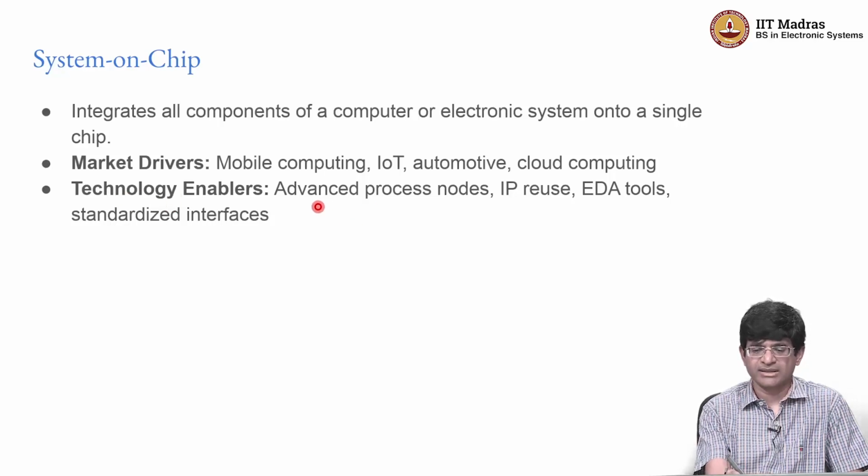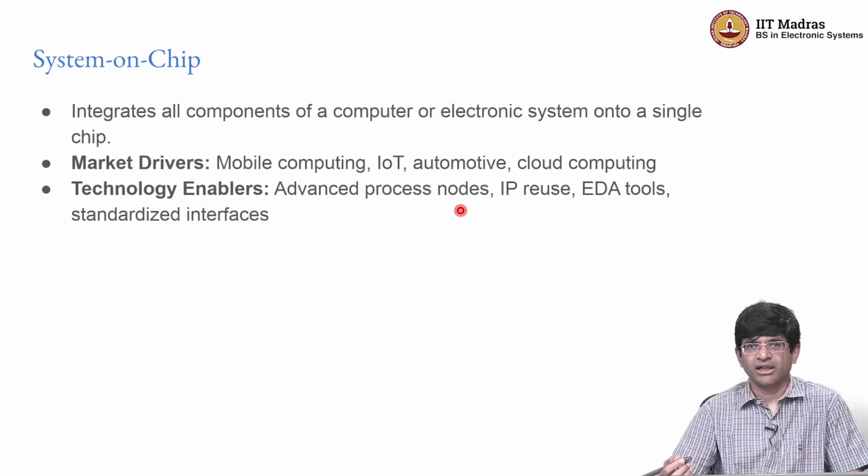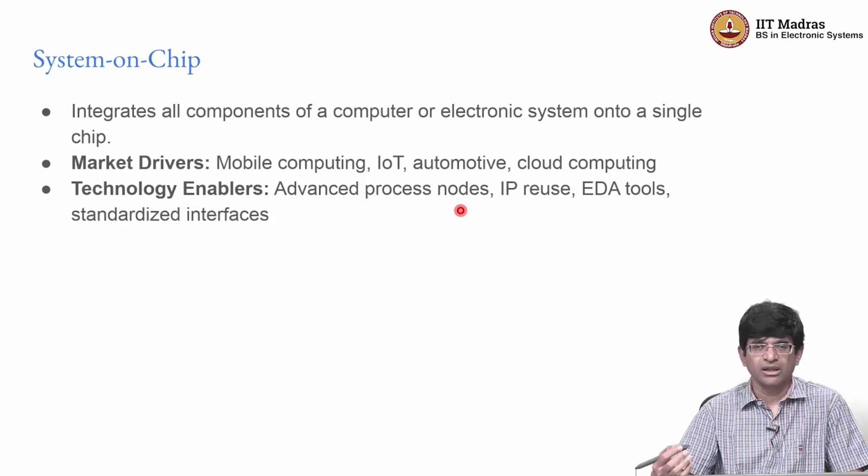The technology advances. Advanced process nodes, you keep hearing about things like, of course, 180 nanometer, which is considered old at this point. It's no longer used for the latest processes, although it is still commonly used for slightly older and more applications that do not require extremely high performance, but do require things like robustness against supply voltage fluctuations and things of that sort. But advanced process nodes now go all the way down to 5 nanometer, 3 nanometer, and possibly even sub 2 nanometer feature sizes.